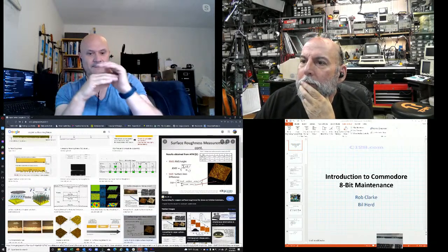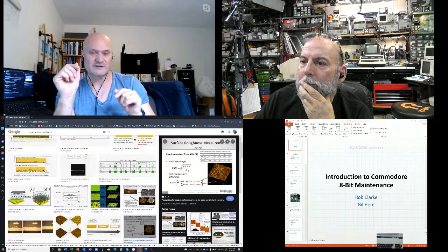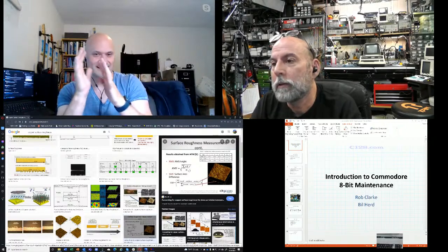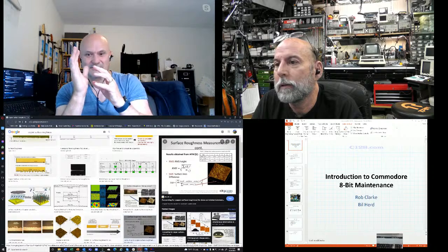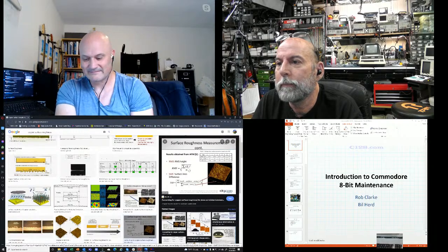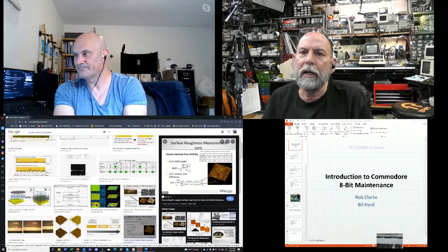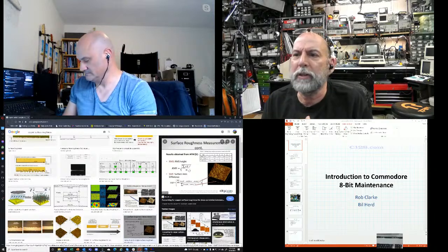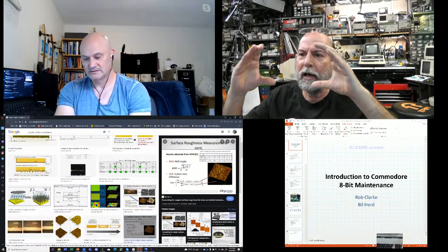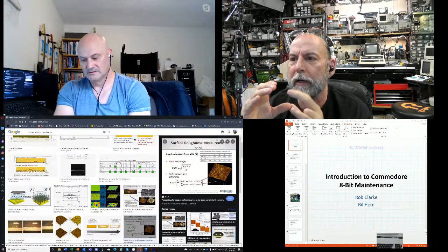And you go 2 inches across the printed circuit board, and at the other end you measure it and your eye is almost shut, and the chips have a hard time detecting what's a 1 and what's a 0. And also I've heard that in the eye diagrams, what we end up with is edge detectors, so it's also the rate that it gets to that high or low, which contributes to the size of the openness of the eye diagram.